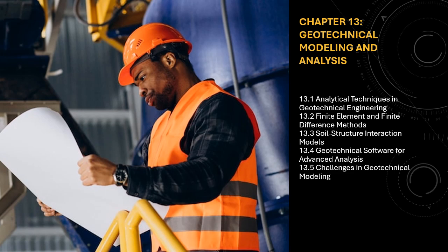13.2.1.1 Basic Principles of FEM. Discretization. The first step in the FEM involves discretizing the continuum into finite elements. Each element is connected by nodes, and the behavior of the system is described by mathematical equations that relate the displacement and stress at these nodes.